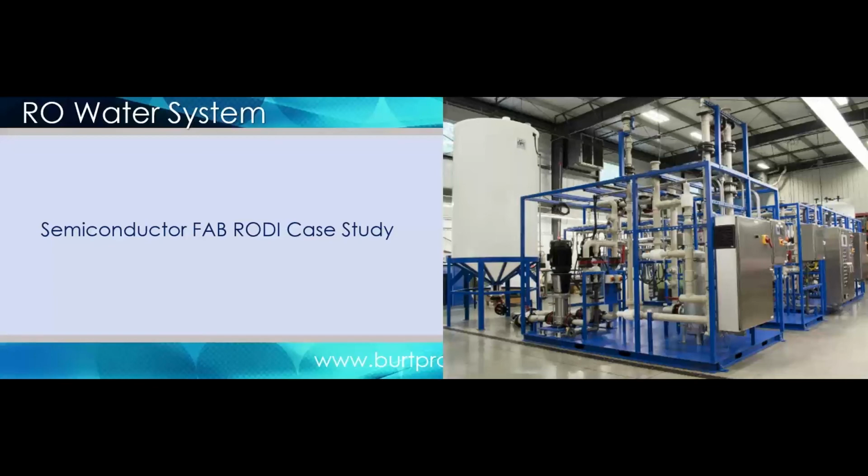If you are doing it with peroxide, it's a very similar scenario. Steam and hot water. Hot water, they typically heat up the storage tank, which is then full of high purity hot water, and then they flush it through the system essentially to clean it with hot water. It's very common in the pharmaceutical industries. Okay, so you have a couple different options, and it's case by case usually. It is case by case.